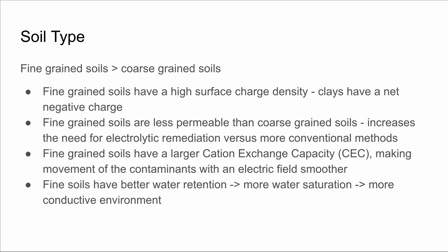So one of the main influencing factors is soil type, and in general, fine-grained soils are more suitable for this process than coarse-grained soils, and that's for a number of reasons. First off, fine-grained soils have a high surface charge density. Clays actually carry a net negative charge, and clays are a very fine soil grain. So you need that charge in order to create a conductive environment for the actual process to take place.